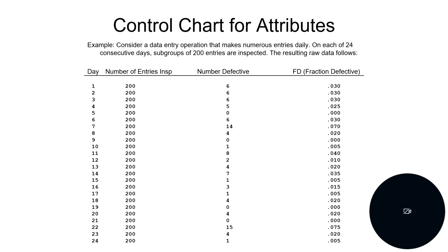So control charts for attributes. I'm not going to solve this problem, I'm just explaining. When we are measuring continuous data, these are our variables. There are two primary charts that we're going to be looking at, which are our X-bar chart and our R chart. The X-bar chart monitors the central tendency, which is the average of the process, while the R chart monitors the process dispersion, which is the range or the variation. So we would use the X-bar chart to track the average bolt diameter and the R chart to track the consistency, or the range, of those diameters.